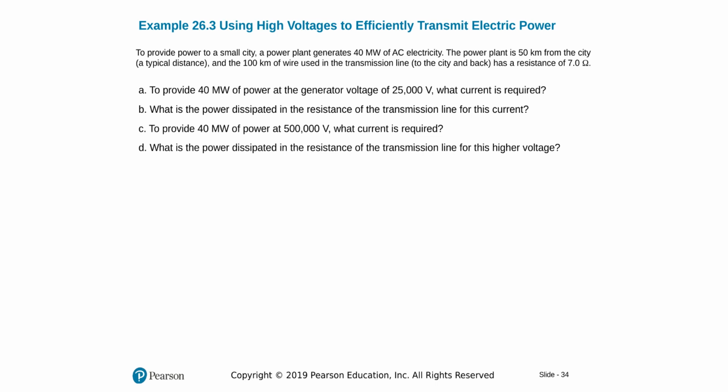Hello my friends, in this video I will solve two problems related to AC currents, and one is about how we transmit the AC electricity through transmission lines and why we want to transmit them at high voltage. We talked about this theoretically, saying that if we transmit them at high voltages we will lose less energy, so less power will be dissipated through the transmission lines, and this question is showing us that numerically and proving that